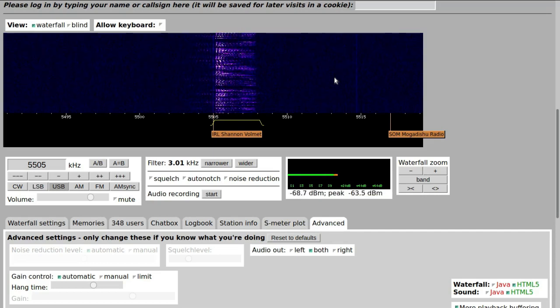There's actually another function called the gradient descent function, which is how it can randomly pick and poke around in the spectrum and find components and discern trends. So if the person is changing the pitch of their voice, or if we're listening to CW or something else that is more coherent and it's moving in frequency, the filters will actually track that signal. You can see that Shannon Volmet is not speaking in a perfect monotone. The pitch does go up and down slightly.